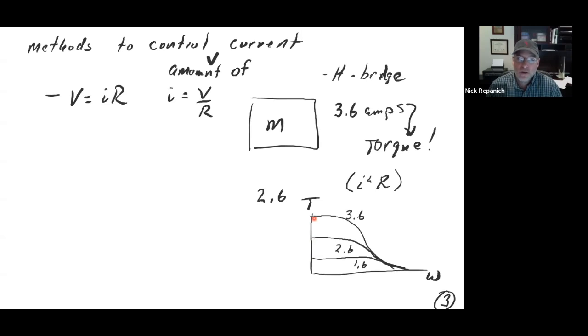No surprise there. And then also going along this axis, the higher voltage you have. So we're starting to get from this, and we'll touch on this a lot more in closed loop, that generally current is proportional to torque, at least within the constant power range, and voltage is proportional to speed.